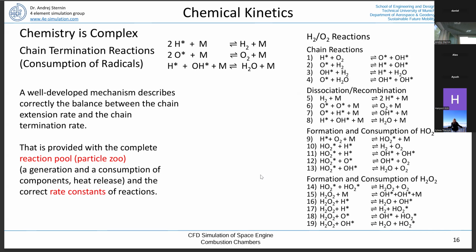That's one of the reasons why some of the k-omega turbulence models do not work properly in rocket engines, because they don't take into account the local heat release by the cooling process. In aero engines, as I said, temperatures are still high enough that the amount of recombination reactions is small, so heat transfer to the combustion chamber wall should be okay.